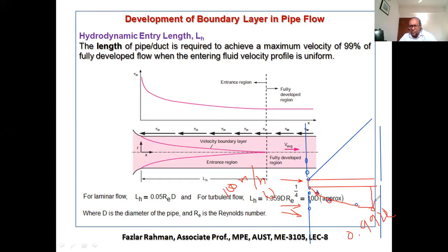Then this portion is called the boundary layer thickness. That means at a distance from the tip, we'll see the fluid reaches a velocity of 99% of the free stream velocity. Similarly, you will have one more at the top. So this area of fluid will move very slowly. Same thing right over here, very slowly.